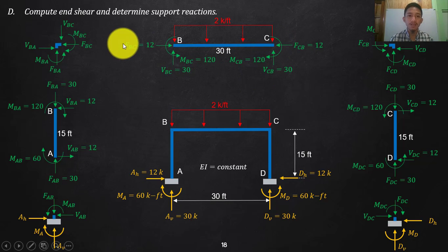I will first forget about your axial forces. Later on we will solve that one from your joints. So now summate moment here. Again, that is just of course equilibrium. You can check that one. So this is going up 30 and going up 30. You can check that to be exactly the same as the total load, which is 30 times 2, is 60, divided by 2 since that is symmetrical. So actually that is 30.